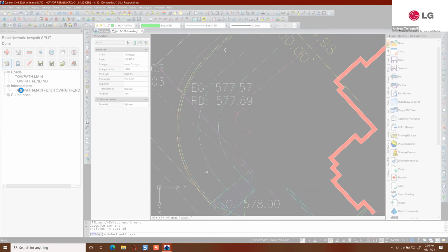It creates the surface just fine. When you turn the intersection processing back on, even though it creates the line work, apparently when it's trying to put the boundary on the surface, for whatever reason, it goes out and grabs that backmost road. It doesn't make any sense from a programming standpoint, except maybe that when it's not processing intersections, it's looking at something different.